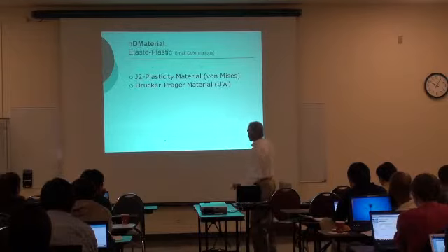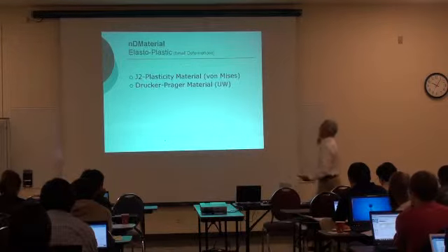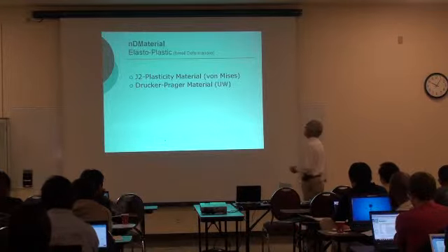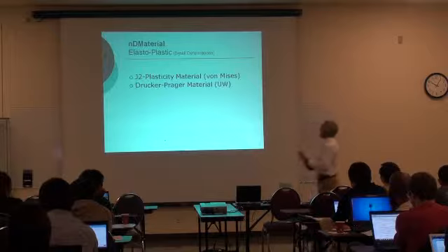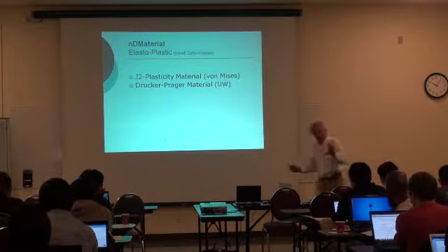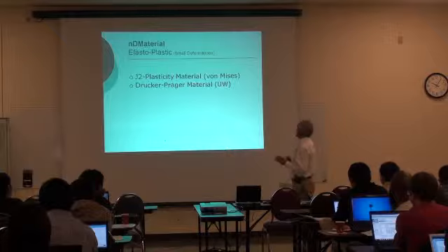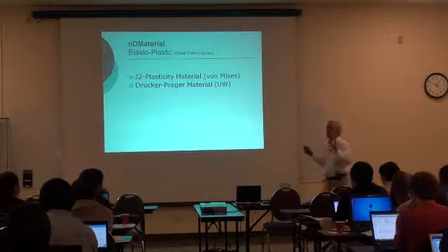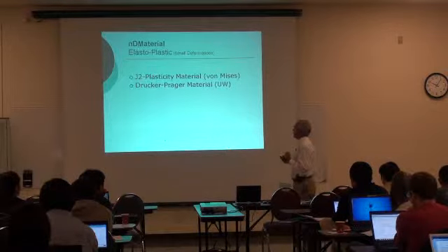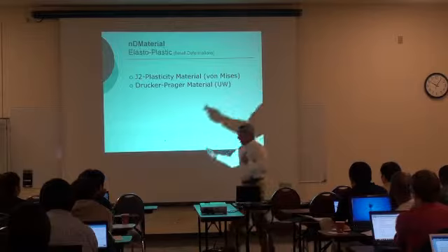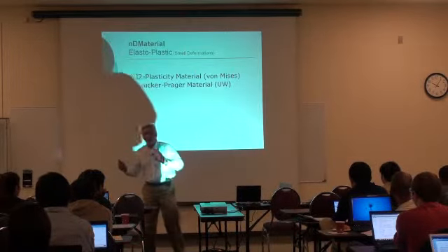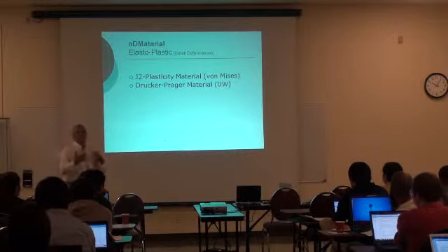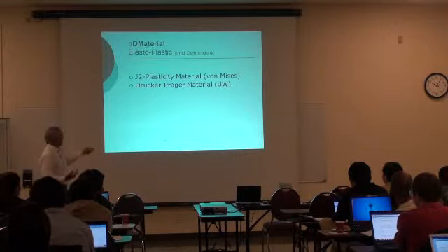Very simple. Now, when you go into the elastoplastic regime for small deformation still, the models that are currently operational in OpenSees are several. First, you have the very simple and classic material models, J2 plasticity of von Mises. That's the most conventional and simple constitutive model that you can use. You can include linear hardening, nonlinear hardening. It could be isotropic. It could be kinematic hardening, and so forth, but it is limited. Limited because it doesn't capture everything that you want to know about the soil behavior.